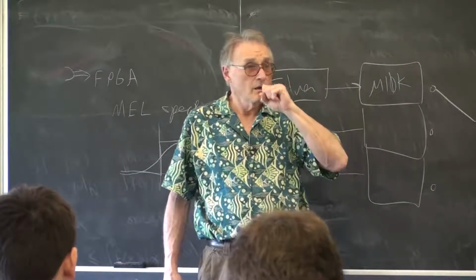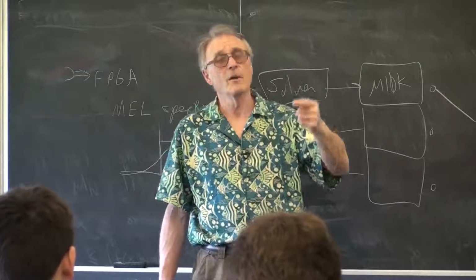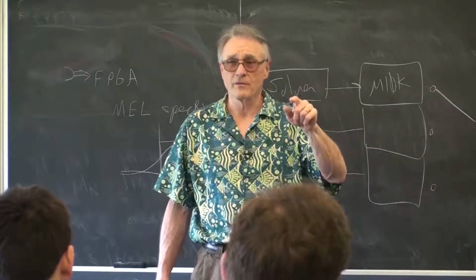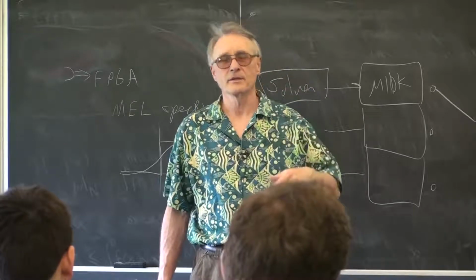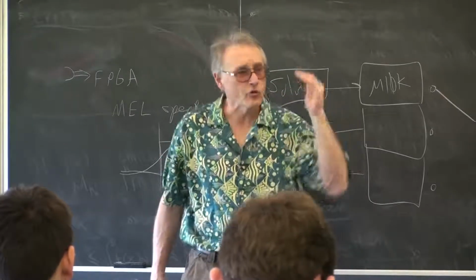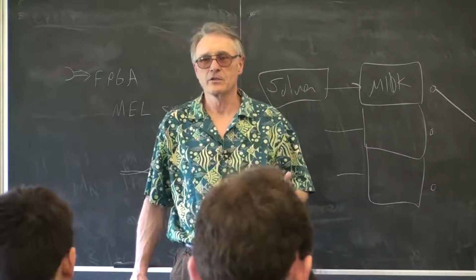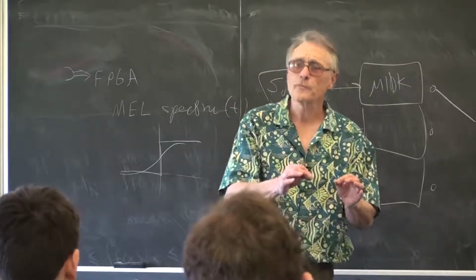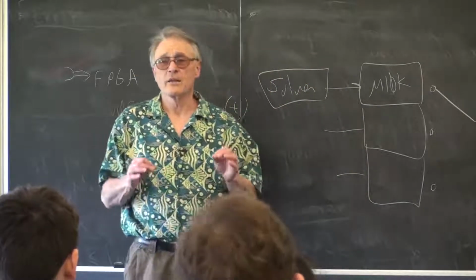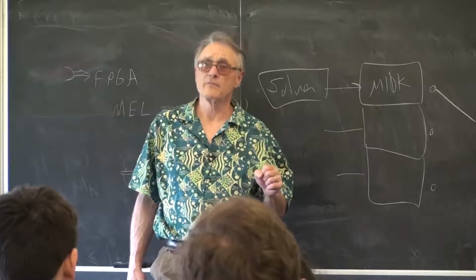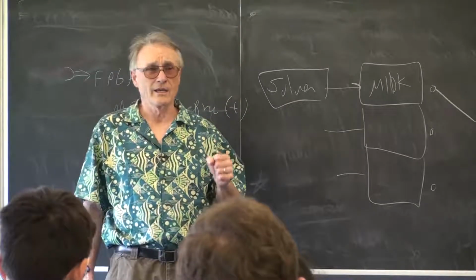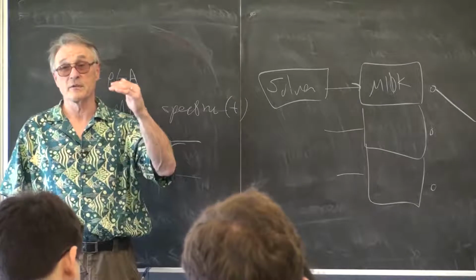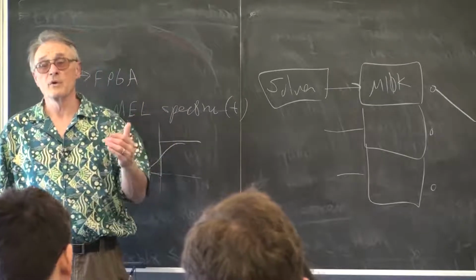So what I did was to set up a write loop, a memory access loop, that was 4 cycles long. Load the address, wait for the ACK, do something else, I forget what it was. And it trashed the VGA controller. It used way too many cycles. So then you can ask, how many cycles do you have to add in before the system is stable? And the answer is 8 cycles. 7 cycles didn't work, 8 cycles did. That says that every 12 cycles, 4 states of the state machine plus 8 wait states, you could write 1 value.